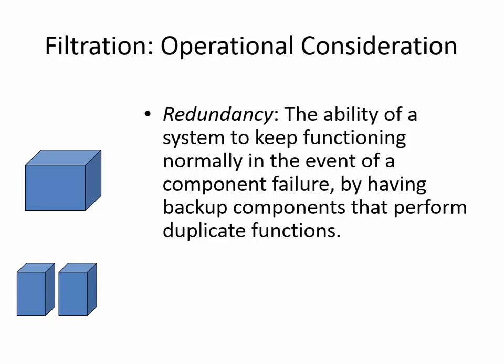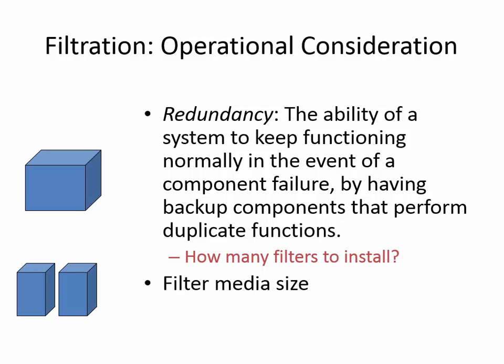So you can go through a cycle of taking one of them offline for repair or maintenance, and then there's backups. That's the issue of redundancy. This diagram is just showing, don't make one huge filter, make a few different smaller filters. So the question is, how many filters do you need? You have to look at how long it takes to backwash to answer that question.